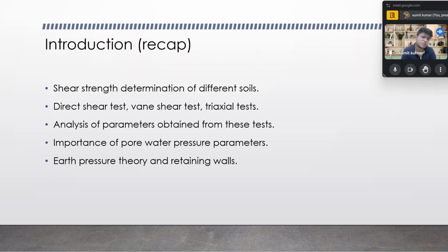There, soils of large particle size, maybe purely sandy soil, can also be tested, and a different apparatus is developed for that as well. The proving ring is there. Nowadays computational facilities have developed, and we get all the results as an Excel sheet. After that, we plot our results to get the value of failure. We are able to plot the shear stress versus shear strain, which we were not plotting earlier in the direct shear test in our undergraduate courses.